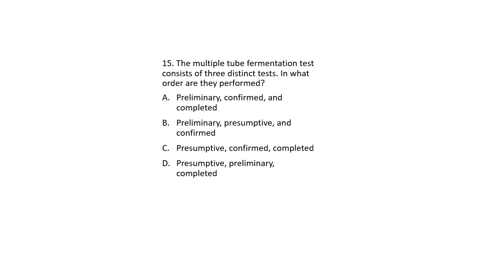Then they do the EC plus MUG, which is E. coli methyl umbelliferyl-beta-D-glucuronide, which I obviously can't pronounce, which will cause fluorescence if E. coli is present. The completed test is rare because you already know it's positive before then, but it gets a little deeper and has microscopic analysis. So the answer on this one is C, presumptive, confirmed, completed.